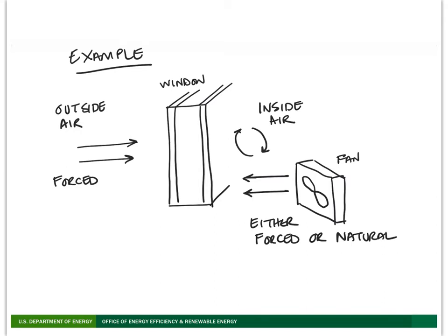You actually oftentimes have an air gap or some sort of a gas trapped between double pane windows. And inside there, you can also have air movement. The interesting thing about convection inside a double pane window is the manufacturers will have designed things like the geometry, the gap between the panes, to optimize the system and typically keep the convection relatively low. So this could be natural convection, but it's probably going to be a pretty small h.